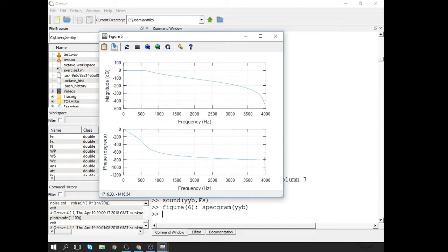So the IIR filters are more cost efficient for this kind of audio processing, since to get a 100 dB attenuation an FIR would take much more time to calculate. It would be higher order.